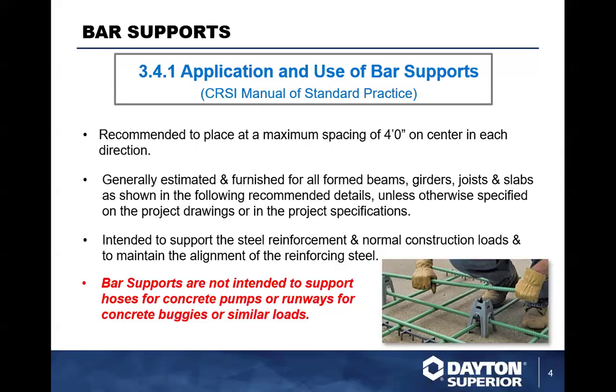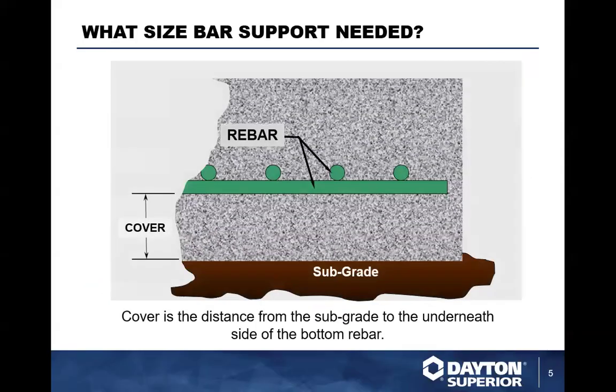So you have to be very careful when you're using a concrete buggy or whatever on a deck, running it back and forth. Although most jobs today, probably the majority of them, are actually pumped in place, so you don't typically have those issues. But let's get started with how you determine what bar support you need, what size? A lot of times you will get a concrete coverage from the ground or substrate to the bottom of the rebar. That is going to be the height you are required to have.